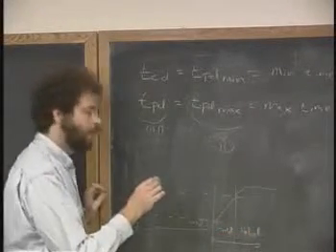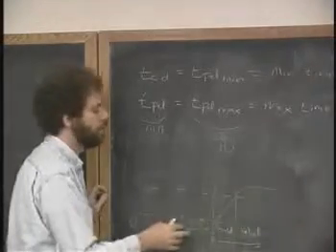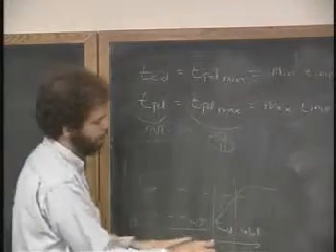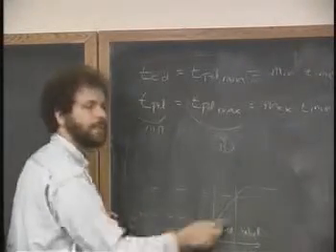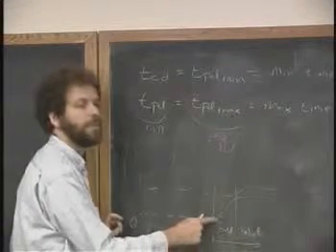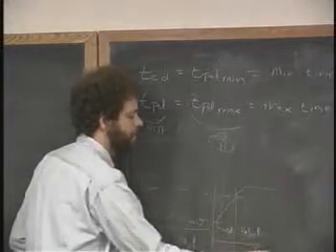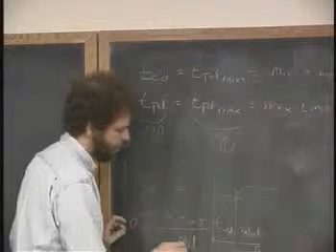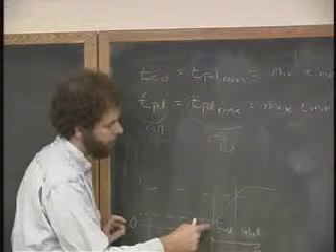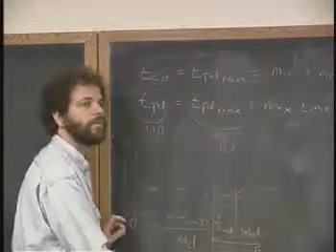Any signal is going to go through these three phases as it switches from a 0 to a 1: from valid to invalid, back to valid once more. And so the question is, if I have a circuit and I feed a signal like this to it, how long does it take between when I no longer am sending it a 0? This is the old value, and here's the new value. The circuit, given the old value, is producing an old result. How long after I no longer feed it the old input does it still produce the old result?